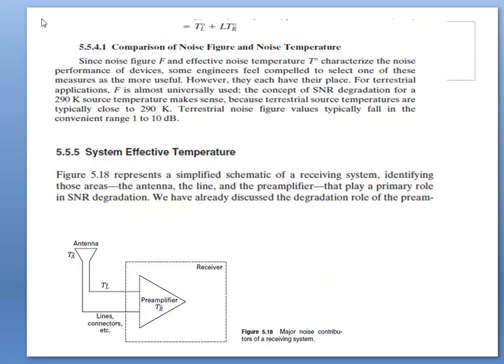The total noise contributed by the external sources can be characterized and is known as antenna temperature. An antenna, like a lens, contributes noise dictated by what the antenna is looking at. If an antenna is pointed at a cool portion of the sky, very little thermal temperature is introduced. The antenna temperature is a measure of effective temperature integrating over the entire antenna pattern.